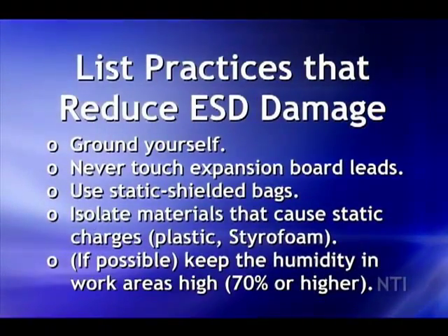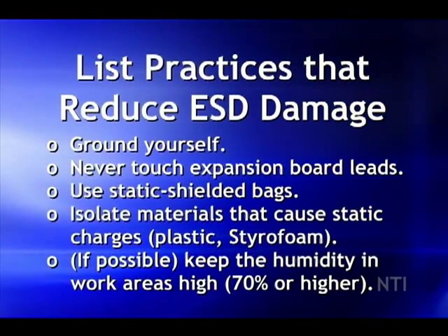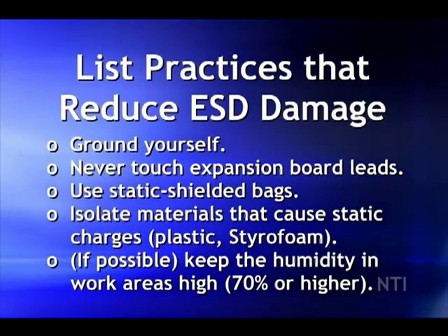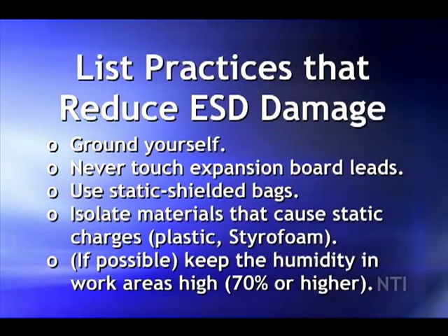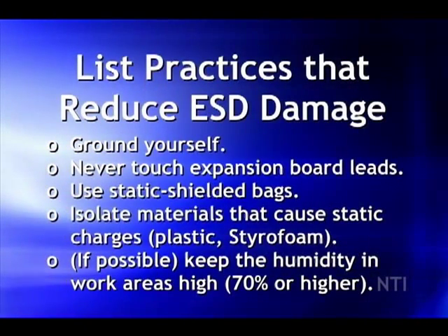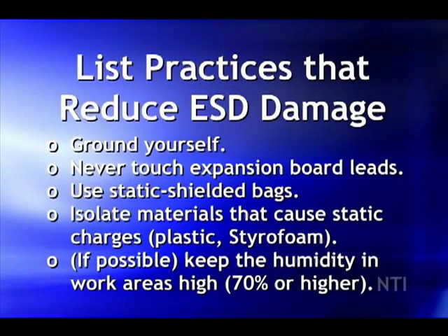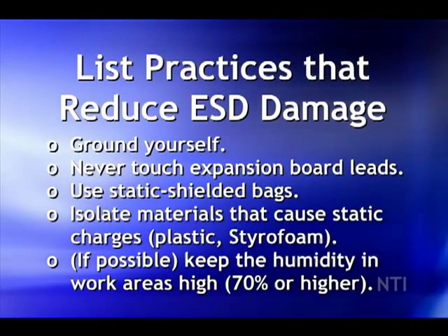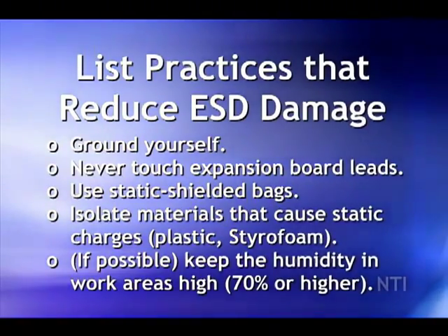Now that we understand what electrostatic discharge is, let's talk about our second objective, and that is some things that you can do as a computer tech to minimize the risk from electrostatic discharge. Rule number one, and the foremost rule, always ground yourself to the computer equipment that you're working on. The reason is, when you're grounded, there's no difference in potential that builds up. Any charge that might build up on you or on the computer is immediately dissipated, and by doing that, an equilibrium is maintained between you and the component, therefore no static discharge can occur.